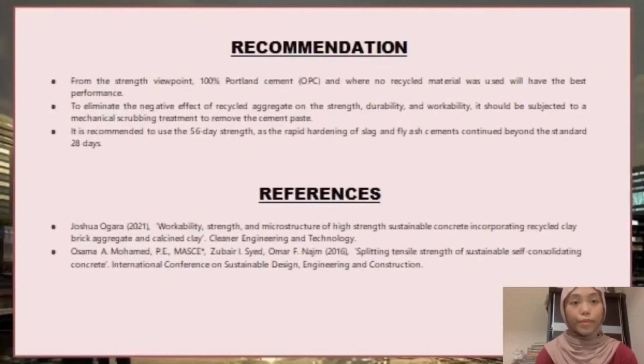Next is the recommendation. It is recommended to use the 56-day strength, as the rapid hardening of slag and fly ash cement continued beyond the standard 28 days.